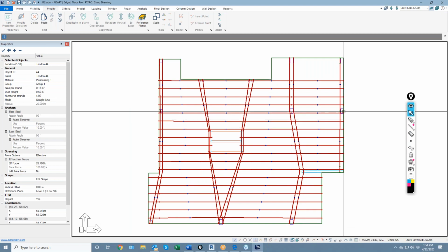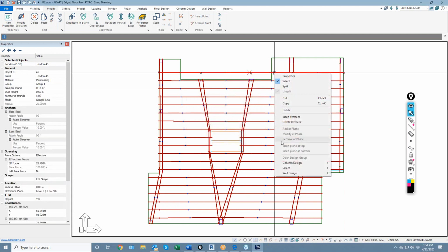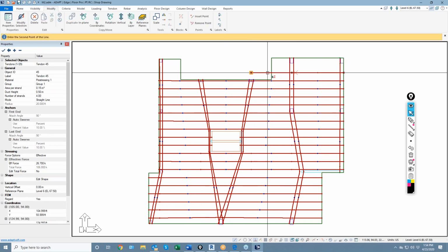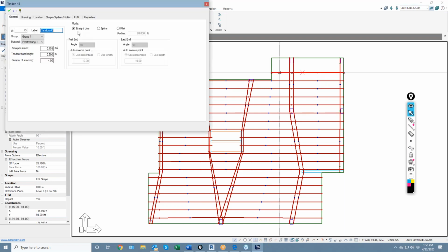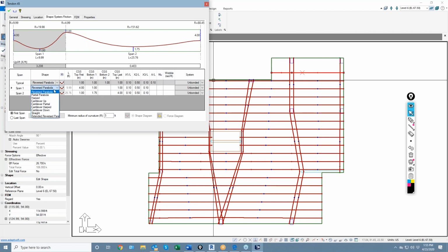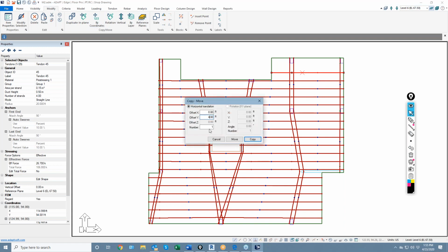And then the last part will be up in this area here. So we'll go ahead and copy that up. Again, I don't have to copy. I could just draw a brand new tendon. The reason I copy is it's just easier for me to edit the cable than anything. So remember, this right now is a reverse parabola. It actually is copied from this span, which is an RP shape. So we're going to go back and modify that to cantilever down, and then copy that tendon up just a couple of times.